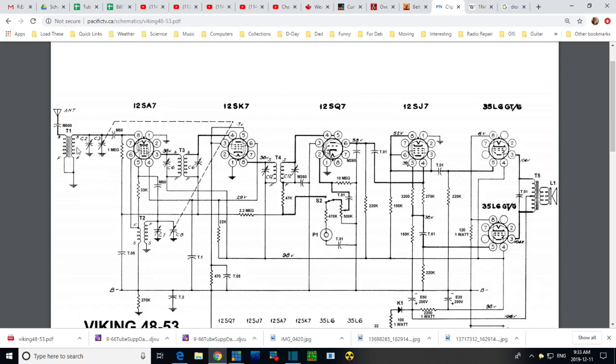So again, there's some of that rejection capability right here, and in fact it's sharp enough that they have to tune it and move it across the band. You can't leave this sitting, say, at 600 while you're trying to listen to something at 1200. You won't hear it at 1200 because this guy is snuffing that out. So these things are not boosting the signal. They are sharpening the response curve to the signal, or creating it, in fact, creating a response curve. You can pretty much put it that way.